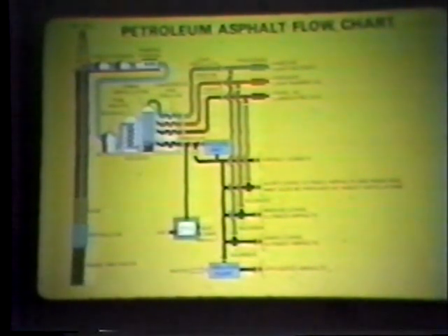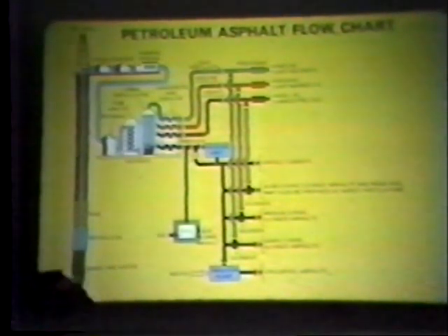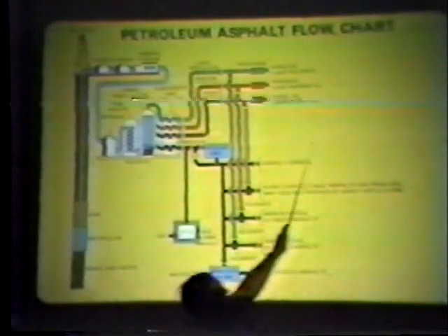If you kind of just glance at your handout, I have located up in here the asphalt cements, all the types that are used across the United States, the pure asphalt cements. If you come down here, you'll have the rapid setting, the medium setting, and the slow setting asphalts listed so that you can see where they come off in the refining process. So you're going to have a good idea when you get out of here today, and you keep this for reference, where all these products come from and how they're made.